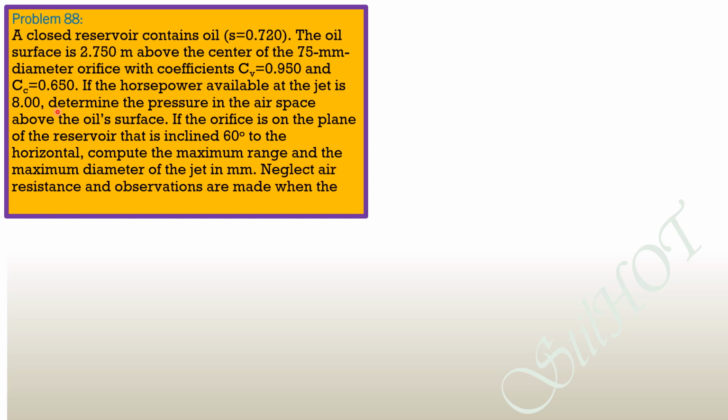If the orifice is on the plane of the reservoir that is inclined 60 degrees to the horizontal, compute the maximum range and the maximum diameter of the jet in millimeters. Neglect air resistance and observations are made when the flow is steady.